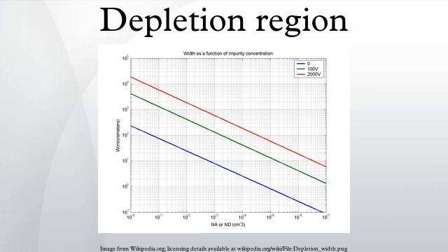In semiconductor physics, the depletion region, also called depletion layer, depletion zone, junction region, space charge region or space charge layer, is an insulating region within a conductive, doped semiconductor material where the mobile charge carriers have diffused away, or have been forced away by an electric field. The only elements left in the depletion region are ionized donor or acceptor impurities.